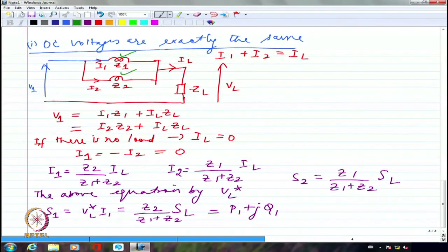If the load is not shared equally, then I will not be able to load them to the fullest capacity of the total transformers put together. Because one of them shares the load much more, it will break down faster. Right? So it is essential that the impedances are almost comparable, if not exactly equal. Exactly equal is very difficult to get, but as much as possible, they should be close enough.